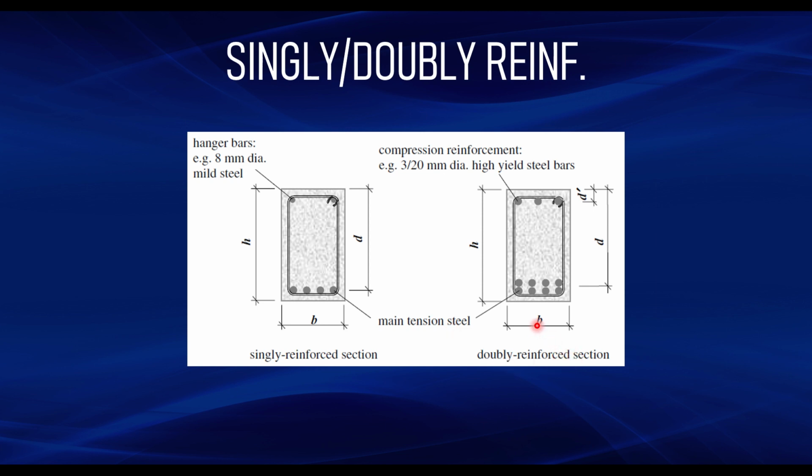But in the case of a doubly reinforced section, this is when the beam is subjected to both tension and compression. So in that case, you need to provide reinforcement for the tension part, which is what we have in the bottom part here. You can see we have a couple of reinforcement bars, about 8 of them, 4 in each layer. Then if you look at the top part of the beam, we have what we call the compression reinforcement. You can see that it's much higher compared to the minimum. It's just because compression reinforcement is required in the design of a doubly reinforced beam.